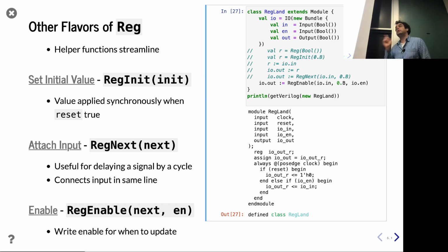Okay, great question. So I want to do a 2-cycle delay. Yes, you could do a regnext and then wrap that in a regnext. Definitely. There are other utilities in the standard library to do, like, a shift register, multiple registers in a row. Most commonly the one you're describing is what's called a pipe. I'm actually going to be building things like a pipe manually in some of the next few lectures just to show some of the generative programming models. To show, okay, if you want to generate registers in a pipeline, the various ways of doing it with recursion, with iteration. But yes, for the question right now, you could just do regnext and then wrap that in regnext, and that'll give you 2 registers in a row.